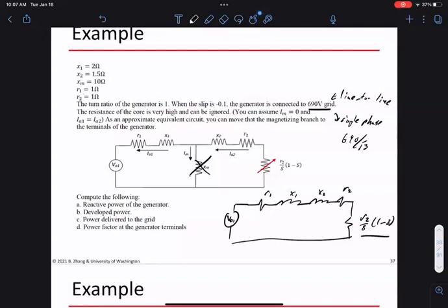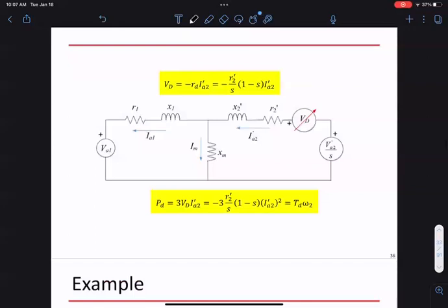Any other questions? I've got a quick question. Sure. In the original model drawing, we had a voltage source on the right-hand side, V2 prime over S. Can you explain why that's not included here? Right, good. Here I have this V2 prime over S. This is if you have some voltage at the rotor, so you have an exciter in the rotor, or you can maintain a voltage in the rotor. In most problems for type 1, we don't have an external voltage source we have access to in the rotor. So that V2 prime is 0 for type 1 and type 2.